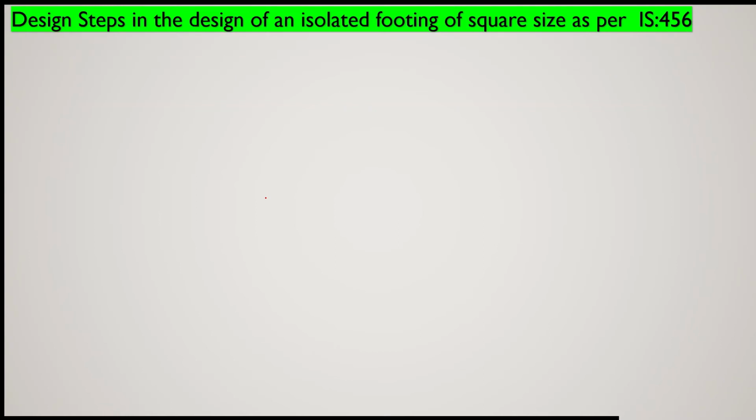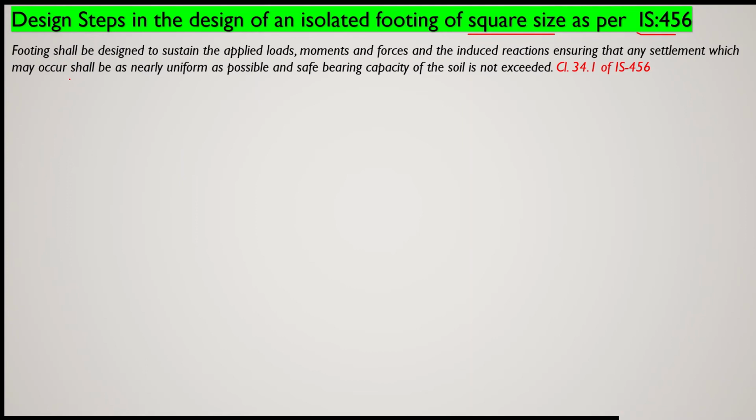Now let us go through the design steps when we have to design an isolated footing. Particularly here we are going through the design steps for a square footing, or it may be a rectangular footing, as per the guidelines of Indian Standard IS 456. Now if you refer to clause number 34.1, it states that footing shall be designed to sustain the applied loads, any movements and forces, and the induced reaction if any,